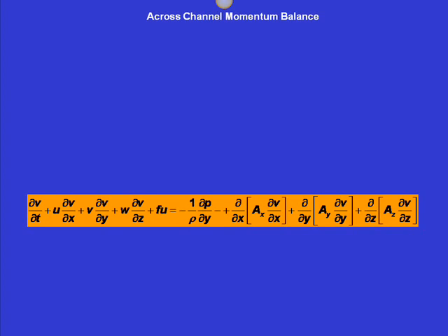We said that for a typical partially mixed estuary, the dominant dynamics is between the pressure gradient and friction, right? So the flow would consist of a near surface outflow and near bottom inflow. And then we said that for fjords, the pressure gradient would be balanced by advection. And for a salt wedge estuary, the pressure gradient would be balanced by advection and interfacial friction, right? And what other momentum balance did we cover? We covered 4 types of momentum balance.